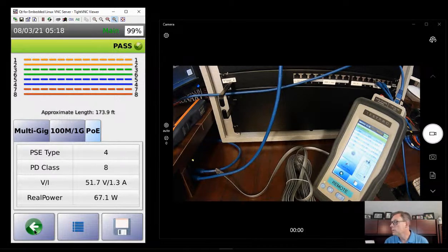And then we could do the same thing. If we ran this test with the silver satin, obviously it's going to fail. If we have a lesser grade patch cord, it would fail. But your first troubleshooting when you're having that PoE issue again comes back to that PoE tool where you're doing a real PoE test on that cable. So that will allow you to go beyond simply pre-qualifying the cable at the time that you certify it.